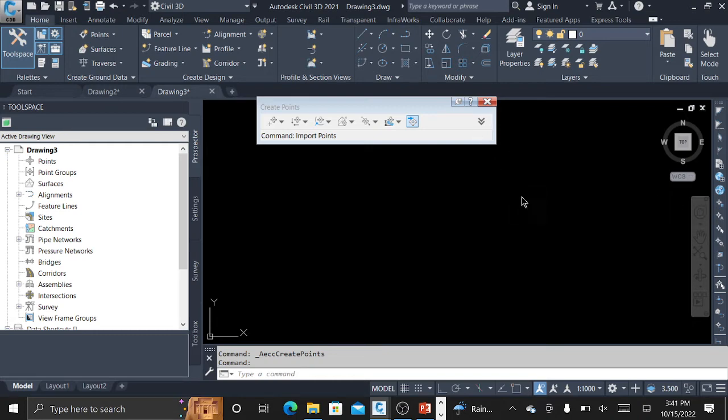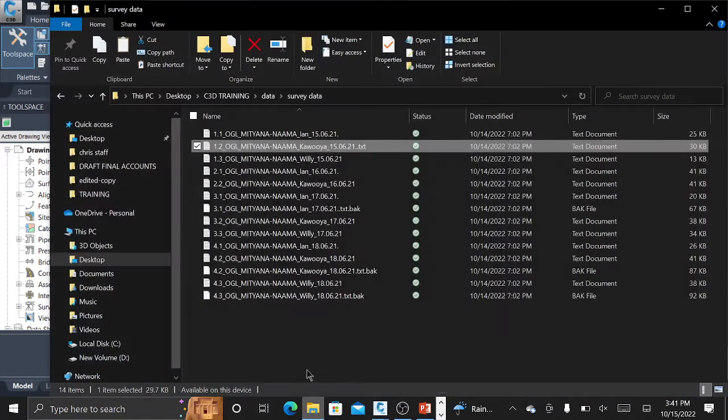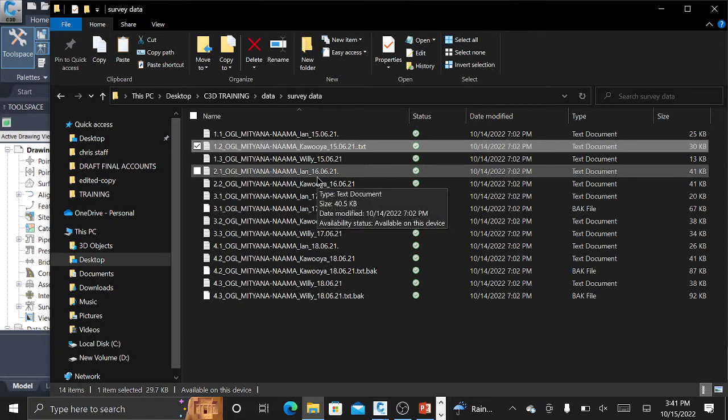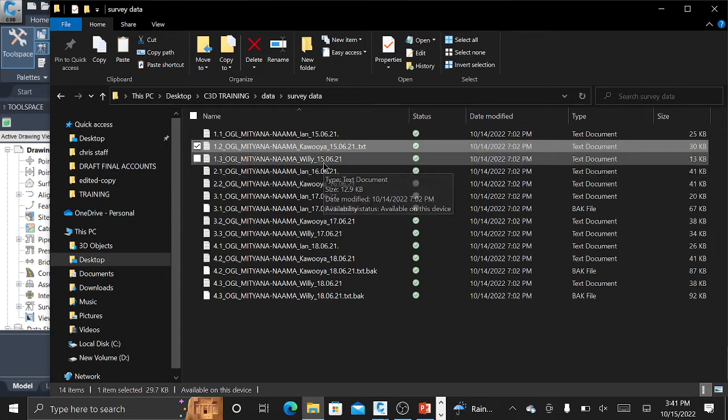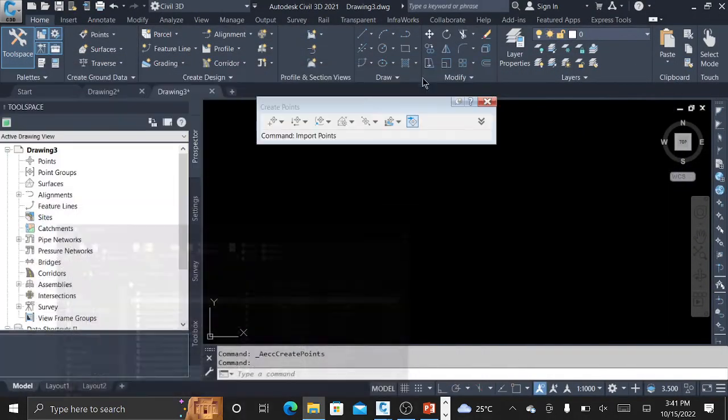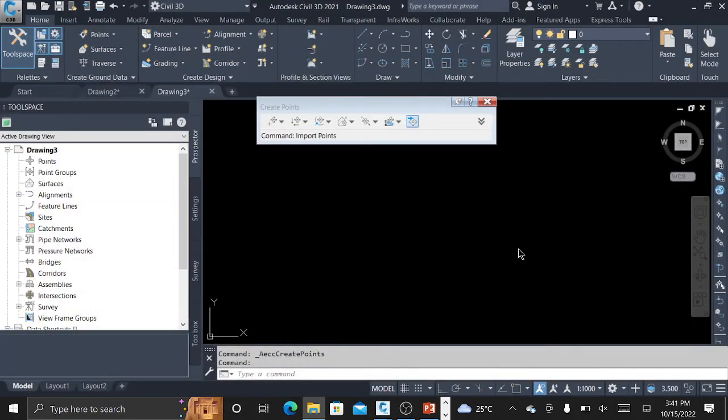The reason we are having that kind of duplication is that the point files were named differently, picked by different surveyors. Each surveyor could have named some points 1, 2, 3, and another also 1, 2, 3, since they are picking points from different sections. So they are duplicating in terms of point number. But you can allow for that, because all we need is to understand the eastings and the northings for the points.